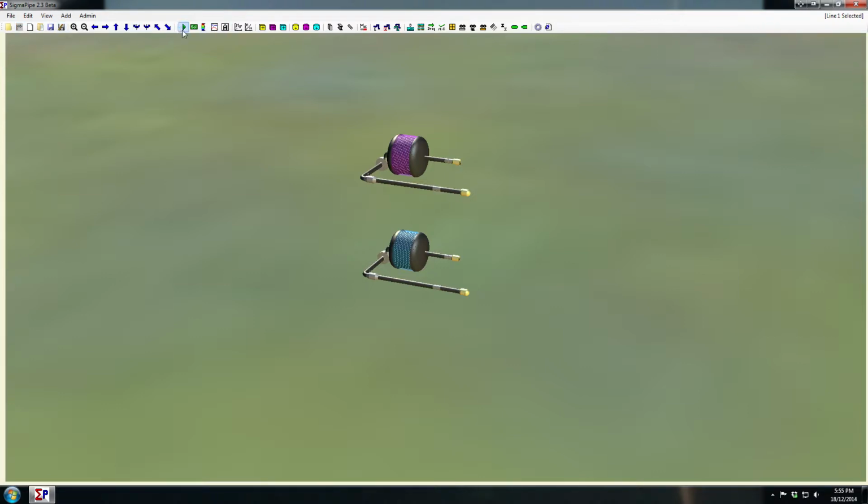Here is your solver, and I guess this is the heart of the system. This is where you view all your data that you're trying to solve for. So here you have the solver, this play button, also the flow solver. You can either solve for a fixed flow rate or you can calculate the flow rate based on the conditions you've set in the program. Here you can graph or view a result graph, which you can graph, for example, your fluid temperature versus fluid pressure throughout a piping system. And here's your stream assay, which is you can look at the properties of a specific streamline, a specific pipeline.